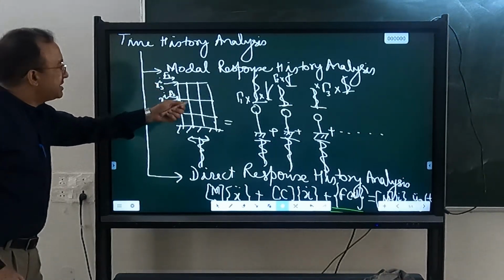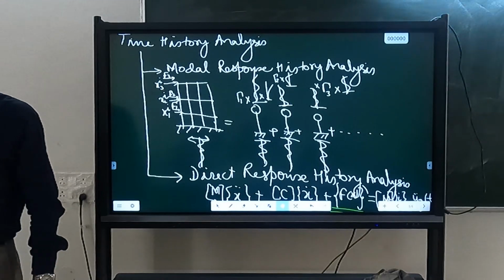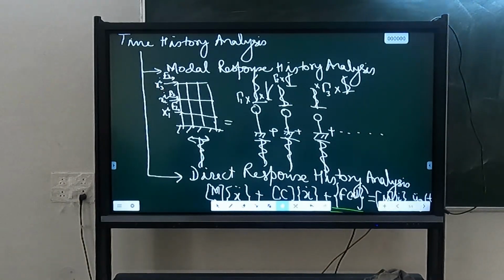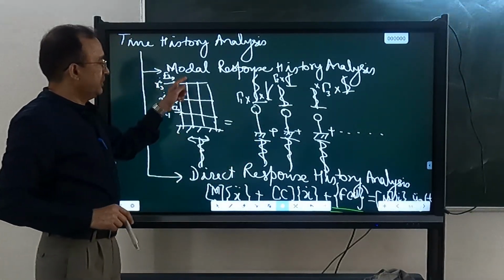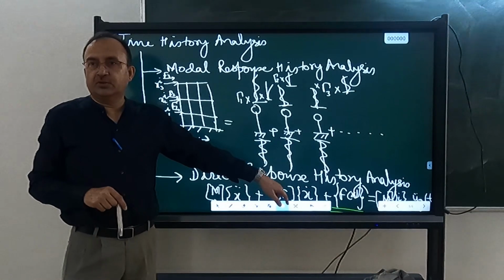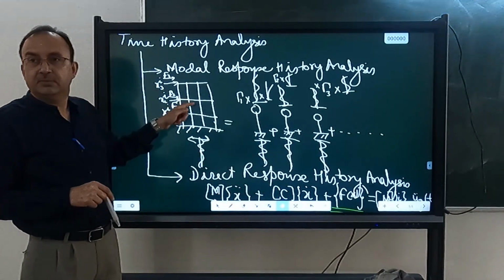Each time we will measure k x from the experiment, corresponding to u double dot g. On the next step you will use that previous k x, again applying that much force corresponding to the displacement we got in the last step. Is it clear now? The displacement we calculate from here and then give it to here, and from here we go back again to this equation, going to the next step.